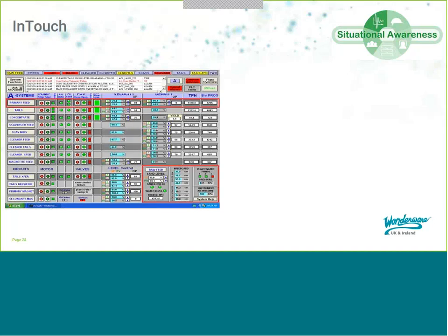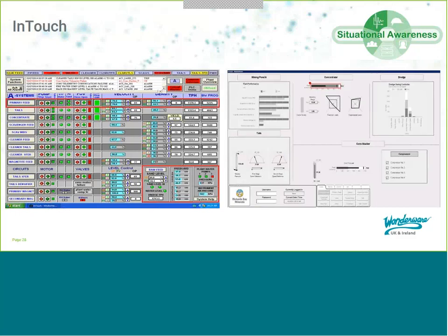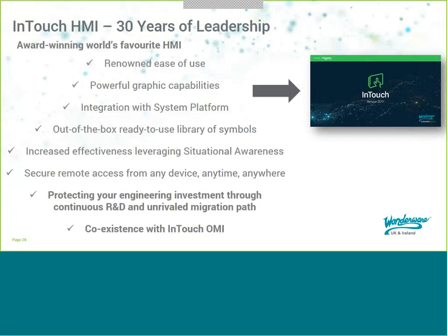If you have a look, our InTouch solution is like any other typical HMI or SCADA solution. So a typical screen you might see is something like that on the left-hand side. What InTouch and Wonderware have tried to do now is introduce the situational awareness design concept. And this just shows a slightly different way of working. Actually the same information is displayed on the left-hand side as the right-hand side, but you can see it's very easy to diagnose and understand what's happening on the right-hand side. But these are things that are built into the solution. So there's an extensive graphic library that enables you to drop a lot of these out of the box.